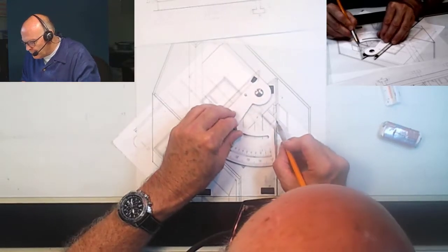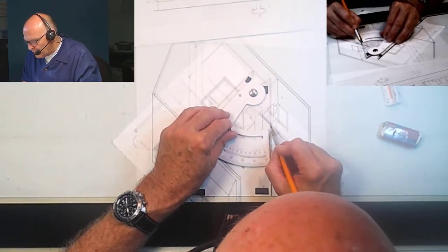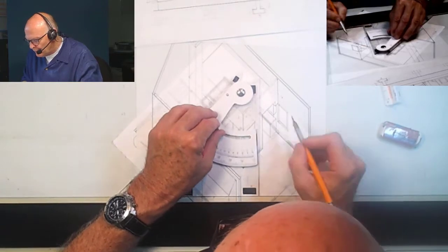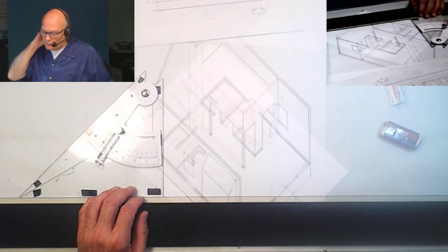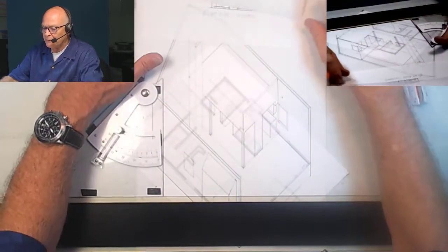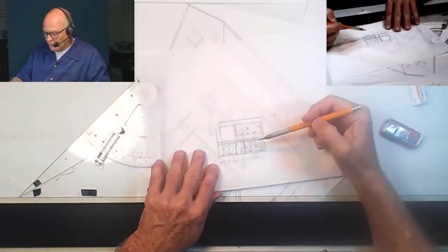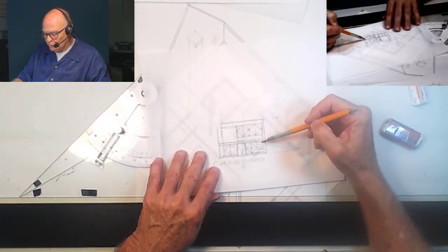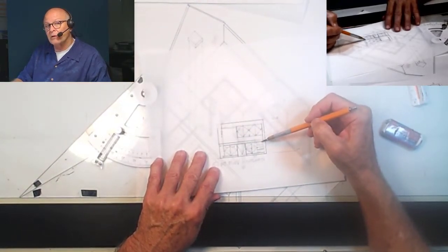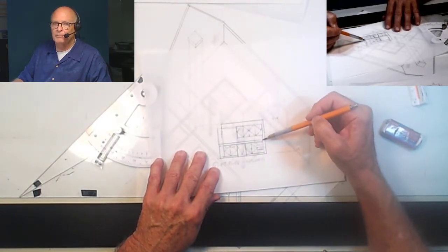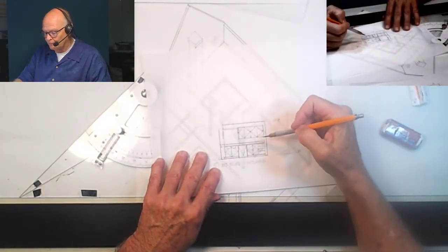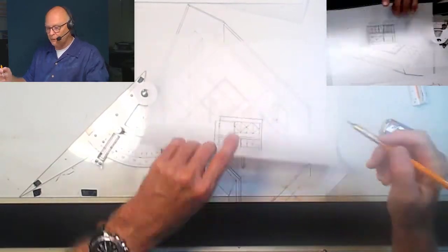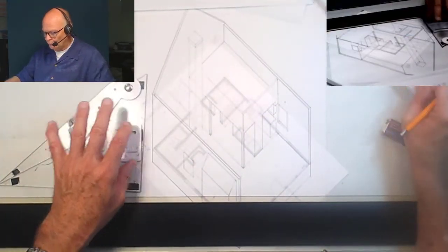Now, we're not quite done. There's a lot of detail that goes on this cabinet, and you've already placed most of it on the interior elevation. So let's go ahead and place that in there. What we have on the interior elevation is we have some drawers. We have a thickness of the cabinet or the countertop. We have a 4-inch splash behind, which is that little piece of countertop that gets extended up the wall. And then we have a toe kick down here.